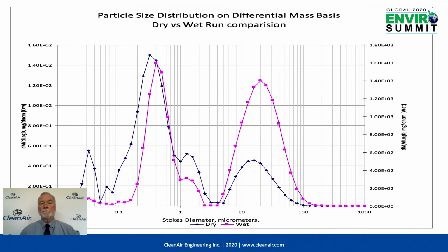So they went right through the scrubber, right through the demister. They're the stuff going out the stack, but that's what you would expect. So when we dried out the sample and removed all the water and then reweighed it, you see what happened is the water that was in this large right-hand peak went away, and we're left with this darker peak. So that dark peak that you see on the right is that dark material by itself dried out that was caught in the pre-cutter liner. You notice that essentially the shape of the left-hand submicron peak is the same, because that material is the same material; it wasn't in a water drop. So this material told the client that they needed to get in, do some serious work on their demisters, and go ahead and repair them.